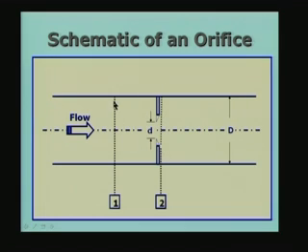So, what I will do is measure the pressure difference between P1 and P2 and use the equation we had, equation number 6, which gives the volumetric flow rate in terms of the measured pressures and the known diameter or the corresponding areas. We can then measure the volumetric flow rate. So, the schematic of an orifice simply shows that there is a small area due to an orifice introduced in the pipeline, so that the flow accelerates, the pressure changes, we measure the pressure difference and then relate it to the volumetric flow rate.